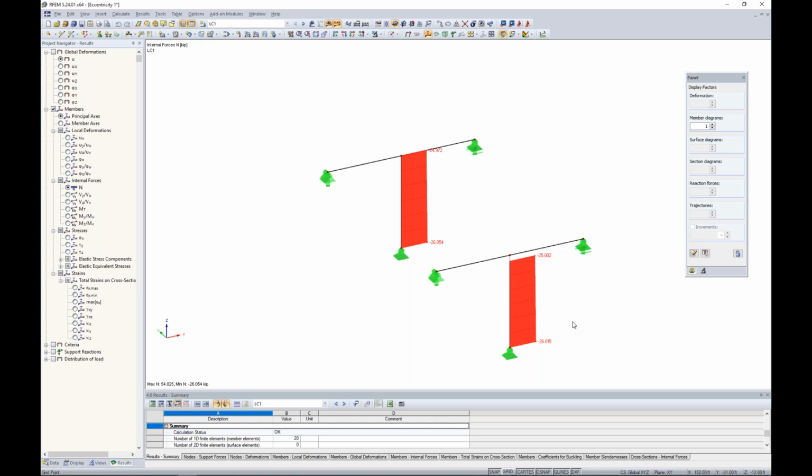So my point being here is that we perhaps have a huge model. We've gone through, we've applied all these eccentricities for our columns to drop that down to the bottom of the beams framing up above it, with absolutely no influence or very, very little influence on our results that really don't make it worthwhile. So maybe not detrimental here in terms of additional forces, but really no difference. So there's no reason to apply these offsets in these situations.